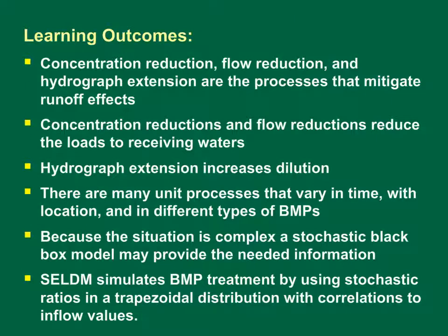In this training module, we learned that concentration reduction, flow reduction, and hydrograph extension are the processes that mitigate runoff effects. Concentration reductions and flow reductions reduce the load to receiving waters. Hydrograph extension increases dilution. There are many unit processes that vary in time with location and in different types of BMPs. Because the situation is complex, a stochastic black box model may provide the needed information. SELDM simulates BMP treatment by using stochastic ratios in a trapezoidal distribution with correlations to inflow values.